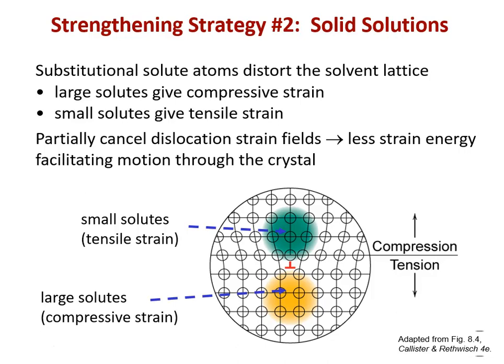Now, it still requires way less energy to move even that partially stabilized dislocation than to move the whole crystal lattice by shearing every plane on the shear plane. We're still orders of magnitude below that, but we definitely will be maybe within a single order of magnitude changing the energy or the stress to move a given dislocation.